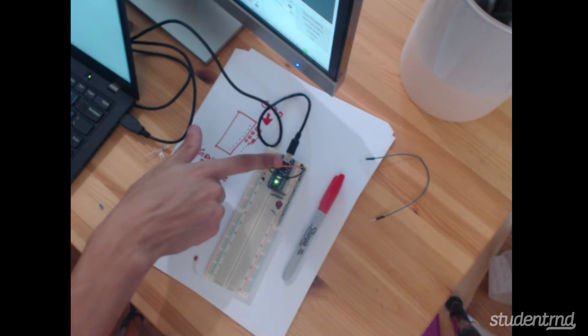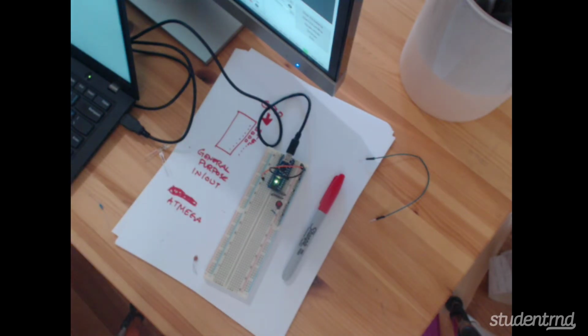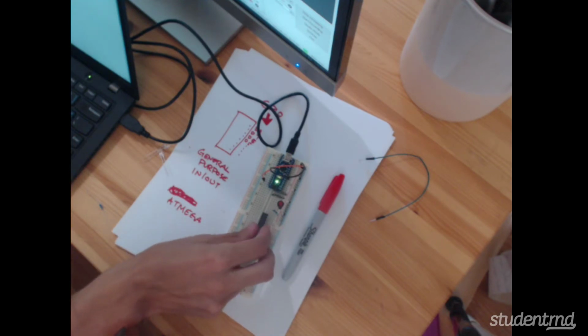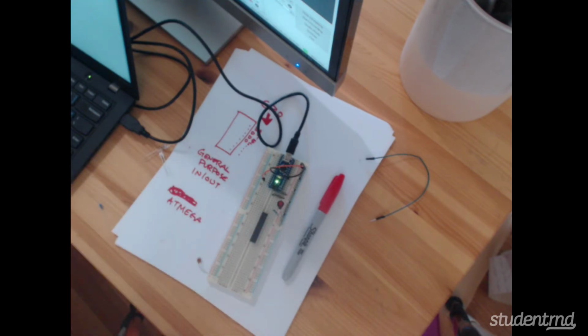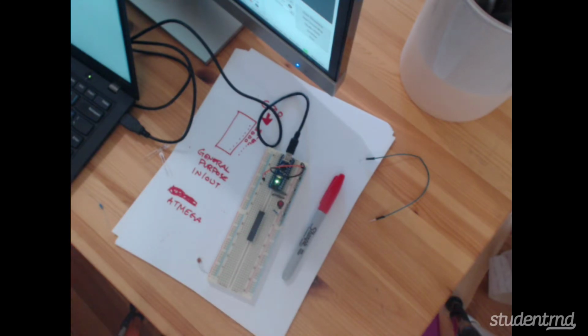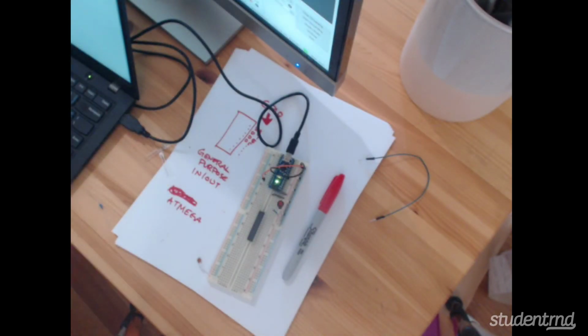You can buy these chips. Obviously, this one is a little bit hard to work with because it's so tiny, but you can buy much bigger versions of them, ones that are this big. And I could actually just directly plug this in here. And all I would need is to reliably provide it 3.3 volts and give it a clock frequency, which you can do with a crystal. And I actually have a few of them. Let me see if I can pull one out. Crystal, which you can buy as well. So you could theoretically build an entire Arduino without using an Arduino yourself.